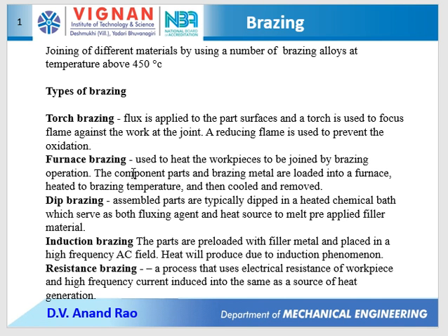And next one is induction brazing. Here the heat required to melt the brazing alloy is generated by the phenomenon of induction. For this we have to supply a high frequency AC field. Due to that induction phenomenon, a high amount of heat will release in the joining metals itself, and finally we can get a brazed joint between the two workpieces.